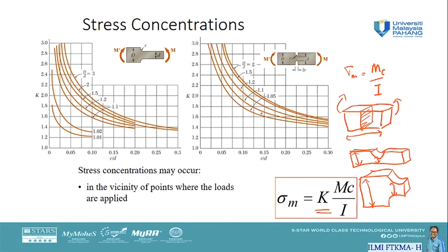Both graphs show that it is very important to use fillets and grooves that have a radius r as large as practical in the application.